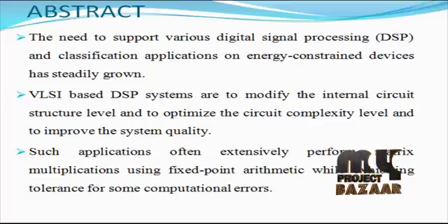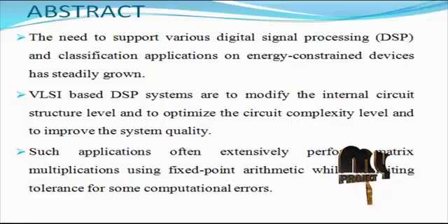Finally, these algorithms are initialized, designed, and trained with floating point arithmetic but often converted to fixed point arithmetic due to the area and power cost of supporting floating point units in embedded computing devices. Although the conversion process leads to some loss of computational accuracy, it does not notably affect the quality of DSP and accuracy of the application due to the computational error tolerance.